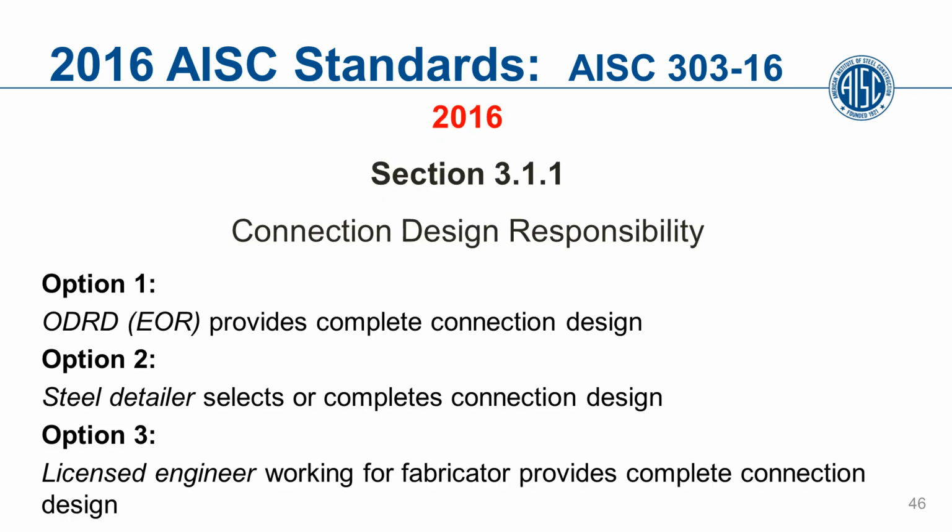So in 2016, there is a change, and the change occurs in Section 3.1.1. There's Option 1, which says the engineer of record provides complete connection design. Option 2, the steel detailer selects and completes the connection design. And Option 3, a licensed engineer working for the fabricator provides complete connection design. Those are the 3 options that are in 2016.